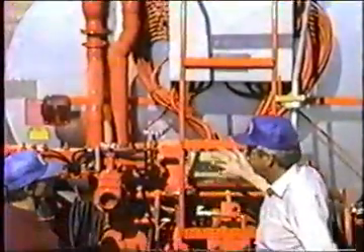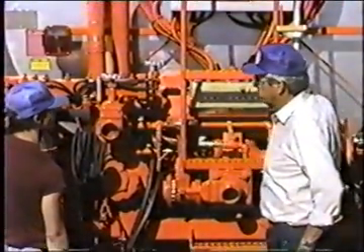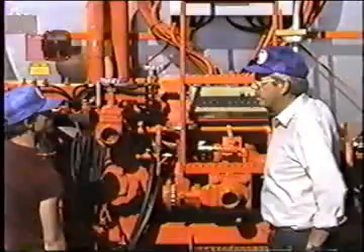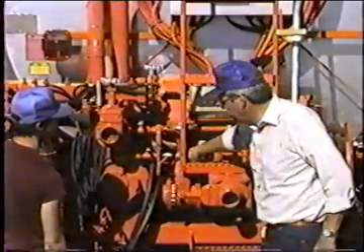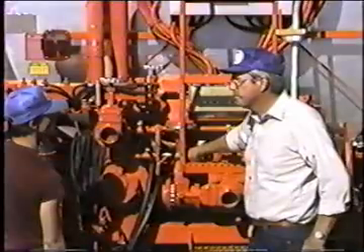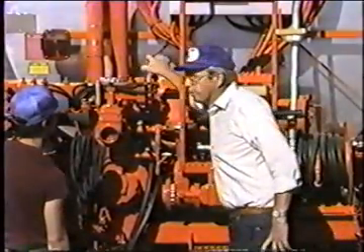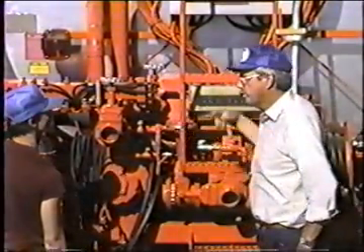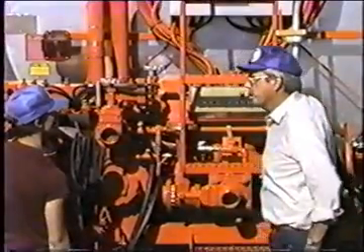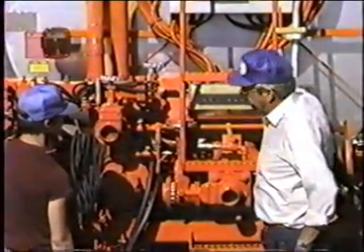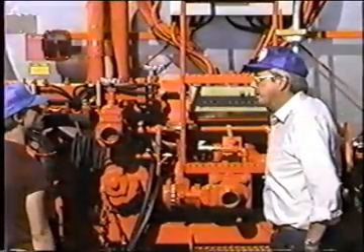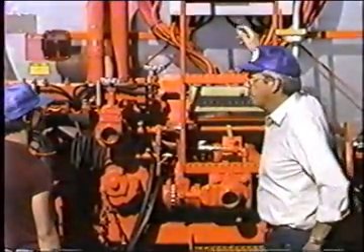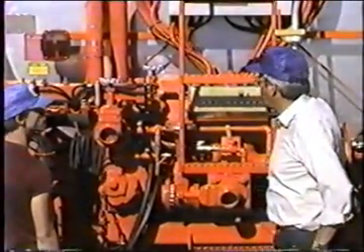Or if we hadn't been heating the truck, if we get to the job and the material's to temperature already, all we're going to do is open the tank valve, be sure this pump isolation valve is open, the spray bar valve, and put the pump in forward and turn it on, put it into the circulate mode. Circulating normally 40 or 50 gallons a minute is plenty. And we do that with the control of the pump in the cab.